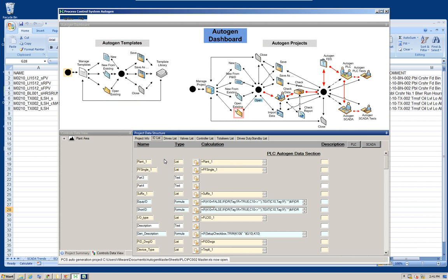Usually customers have requirements for tag construction, and for instance, for the batch control S88 standard, tags are defined by plant location, plant facility identifier, then plant facility sub devices, sub items, control items, and so on. And this is represented here in these first 5 fields. This describes the tag rules in which to form tags.